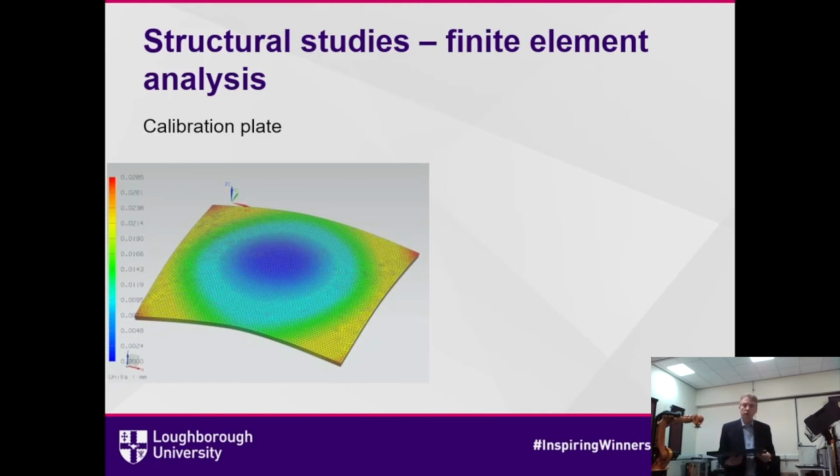Now the problem is that as you move the part around, in this orientation or in this orientation, the position actually moves a little bit due to the gravitational loading. If you imagine it in this position, it's the extreme case. It's a bit like a tablecloth draped over a table. The corners droop down a little bit. Not very much, because this is a honeycomb structure, but nevertheless we had to design it so that the gravitational deflections were small compared to the measurement accuracy.